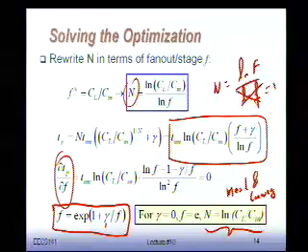In there, they published this result, and they called this the exponential horn. You can see that if you want to drive a capacitor, you make a small inverter and a bigger inverter and a bigger inverter and a bigger inverter, and the sizing factor between them is just equal to e. That's why they call it an exponential horn.